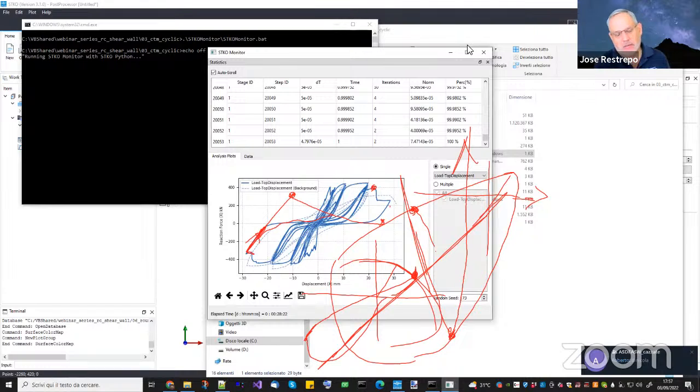And the other things that we're working on here, again on 1D problems mainly, are rate-dependent materials for steel. I think that's a hidden topic, and I think from the shaking table tests we have done in the past, the rate dependency of steel actually can account for much of the damping you need to put at the front end in the analysis.